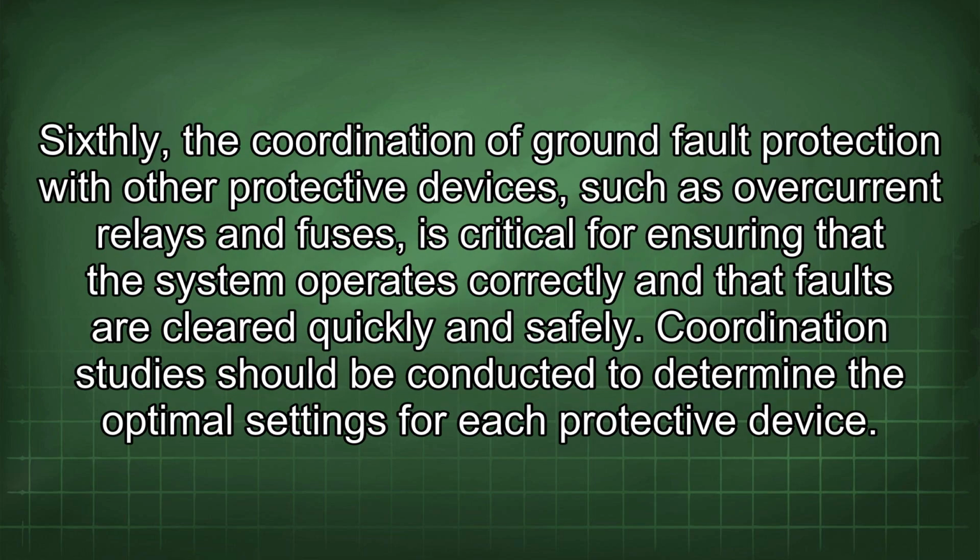Sixthly, the coordination of ground fault protection with other protective devices such as overcurrent relays and fuses is critical for ensuring that the system operates correctly and that faults are cleared quickly and safely. Coordination studies should be conducted to determine the optimal settings for each protective device.